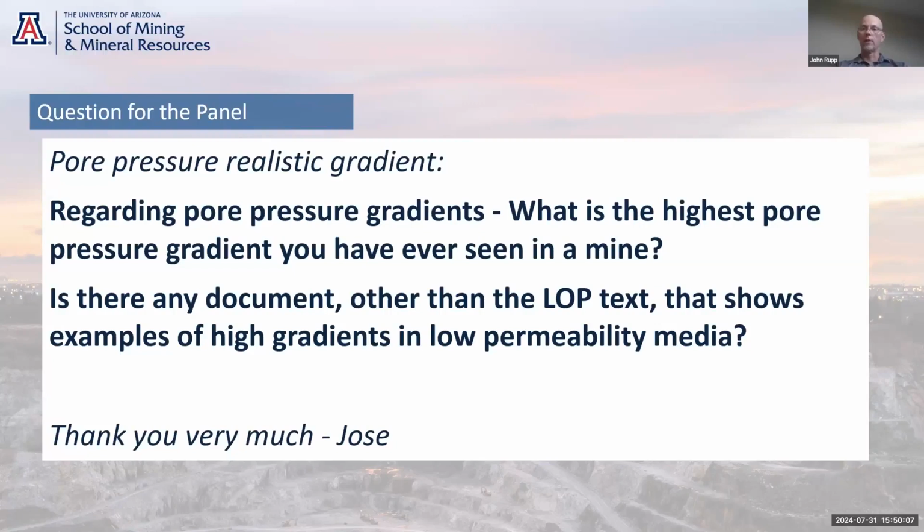Very high, you're probably along some barrier. Unit gradient, you've probably got water draining freely through the vadose zone. And when you have, say, lower than 0.5%, then you're starting to get into a natural lateral flow. Yeah, that's a good point, John. When you have perched water, there's quite a few situations where you can get a piezometer at the base of a perch zone or above a flat-lying structure with quite high pore pressure, and then below the structure or below the contact, there's no pore pressure at all sometimes. So that's a good point.